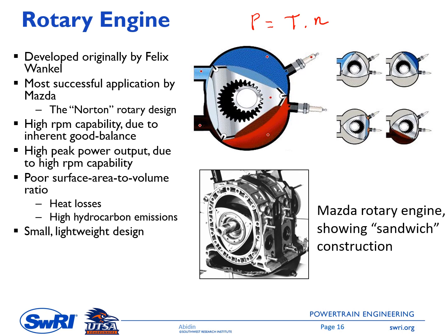For the 4-stroke rotary engine, the schematic is shown in this top right figure. This is the rotor that rotates about the shaft, and this is the intake stroke, where the fresh mixture enters the engine through this port. Next, we have a compression stroke, number 2 here.